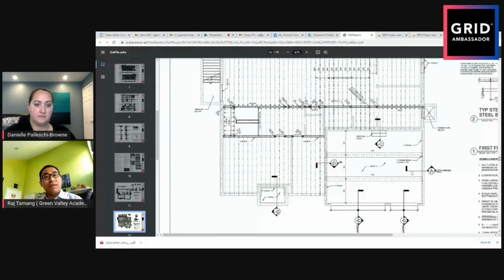Because you have to remember, as a builder, as a contractor, you have to look at all the drawings. You have to look at the grading plan. You have to look at the architecture plan and structure. You cannot just look at architecture and structure only. I've seen a lot of concrete contractors who look at the architecture and structure only. They say, hey, you don't have enough information. Yes, you don't have enough information, because you are not looking at the whole set of plans. I'm not providing all the information in one place, because you're supposed to go back to the foundation plan or basement plan, architecture plan, elevations and grading plan to figure out all the dimensions.